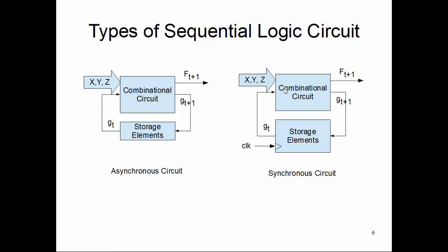Let's say in iteration 10, we pick up iteration 9's partial result, combine them, resulting in F10, and partial result G10 comes in, but it is not immediately handed over. It is stored in the storage element, and at the next clock cycle, depending on the circuit it can be 2 or 3 clock cycles afterward, that is immaterial, but not at this moment, G10 gets handed over to the output of the storage element, so that it may contaminate the F10 result.